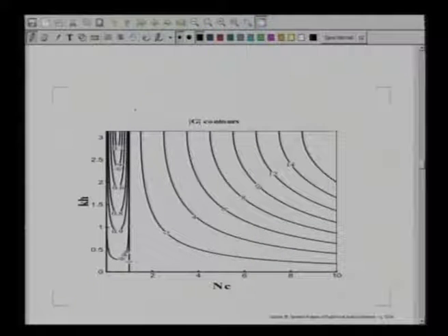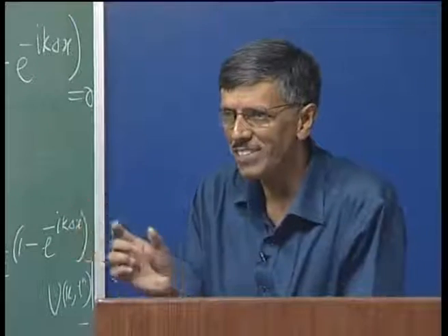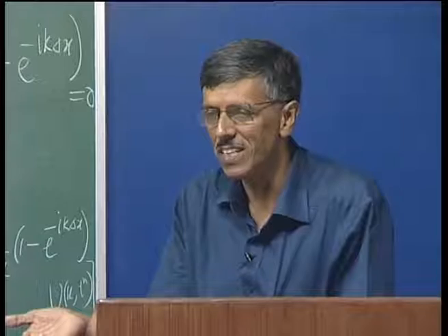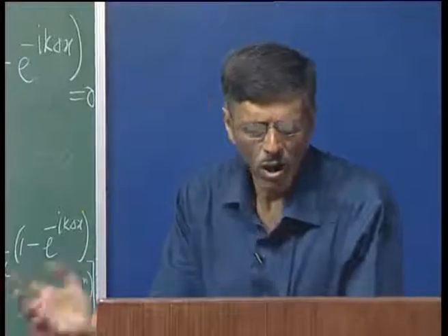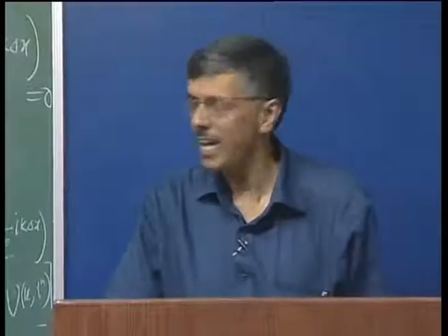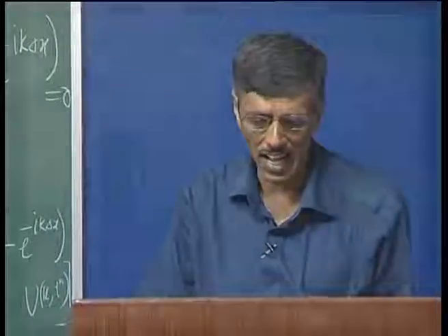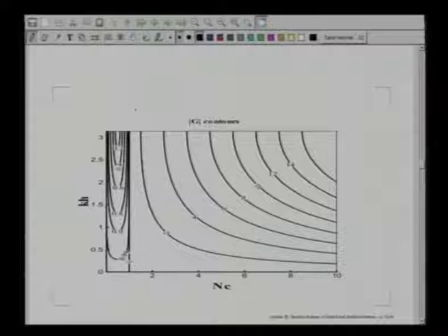That means every time step your solution is travelling by one node, and that is the definition of phase speed c. So you can very clearly appreciate what has been achieved here: you do get the exact solution for n c equal to 1. If you take more than 1, you are unstable. If you are less than 1, it is stable, but it will be erroneous.